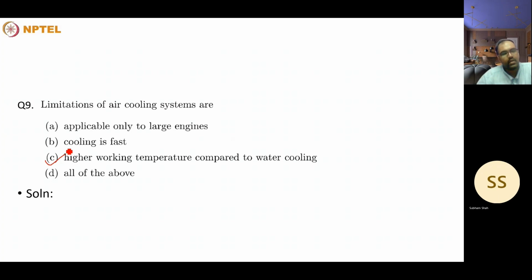It is applicable to small engines, and the cooling is not that fast. So the limitations of air cooling systems are higher working temperature compared to a water cooling system, and it doesn't offer an even cooling compared to a water cooling system.